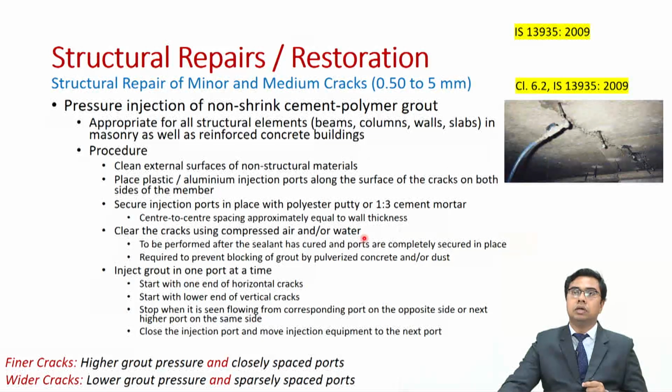and then we will clear the cracks using compressed air or water. So, what we do is that we pump in compressed air or water so that the cracks get cleaned. This is very important to be done before injecting any grout. Why? Because if you do not clean these cracks, then the grout may get blocked and the cracks may not be filled adequately. How will they get blocked? Because of the pulverized concrete or dust which is inside the crack.